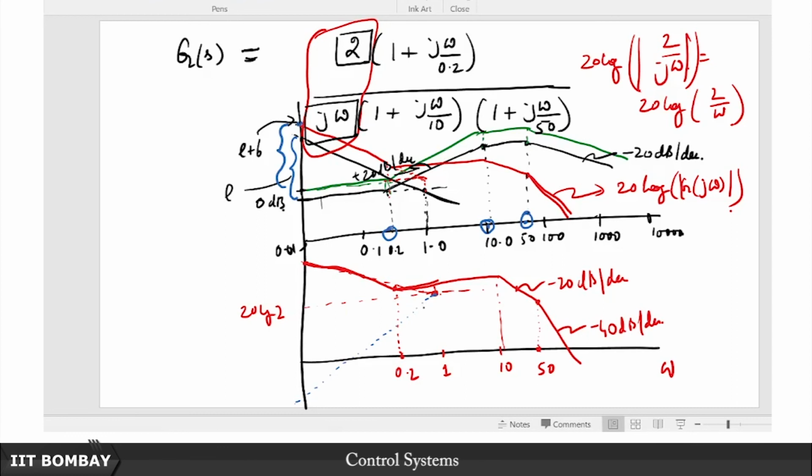So it contributes nothing at this particular value. But if you notice a bit carefully, the integrator and the differentiator have the same slope. So they end up nullifying each other, in the sense that the sum of these two is a particular constant, and what is that constant? That constant is nothing but this additional factor, because at omega equal to 1 the differentiator contributes 0, and whatever contribution is there is due to the integrator.